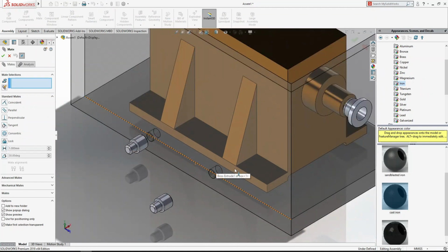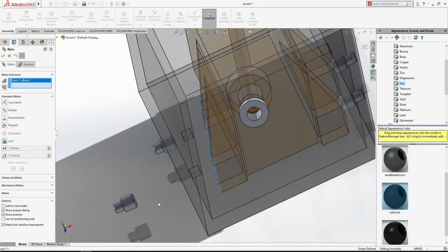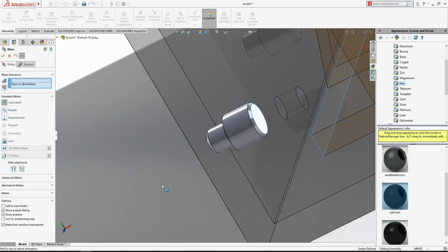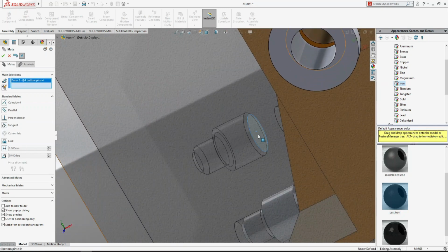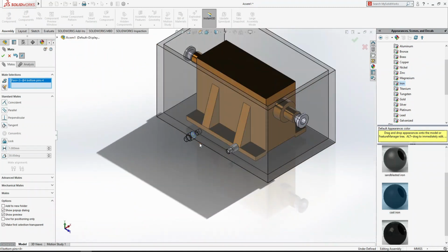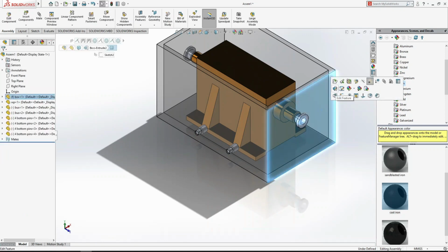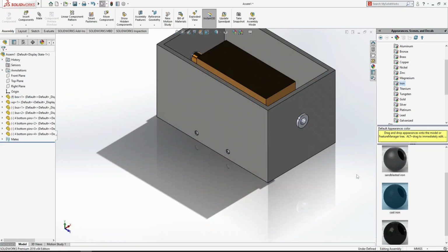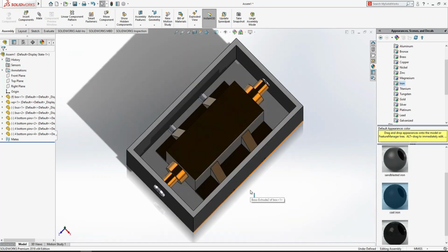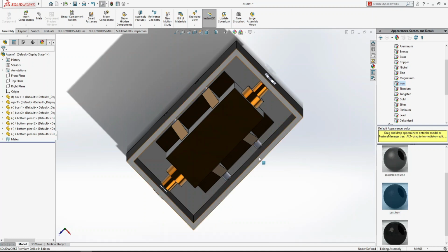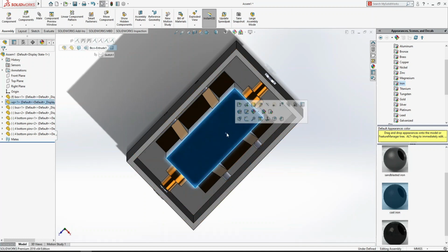Now we need to change its transparency so we can mate the pin. That's the face. Rotate it. That's our head face. Now select the pin. Rotate your part and the face. And okay. Now Escape to exit from the mate. Now Control 7. These two sides are done. One side. Okay, one more thing. Control 8.